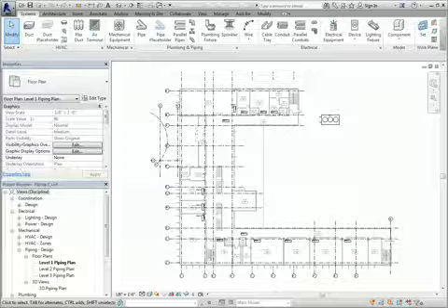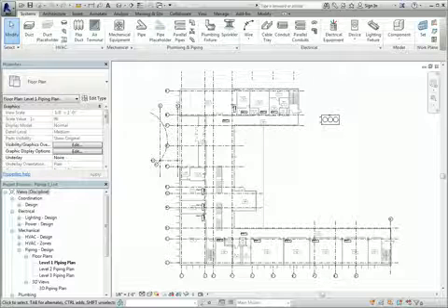Piping systems can be created in two ways. One way is to simply add pipe to connect the water side components, and they will automatically be added to a piping system. The other way is to select the component and manually add them to a system. Then you can have Revit generate and lay out the piping. However, with several components in a system, it's difficult to get the results you are looking for.